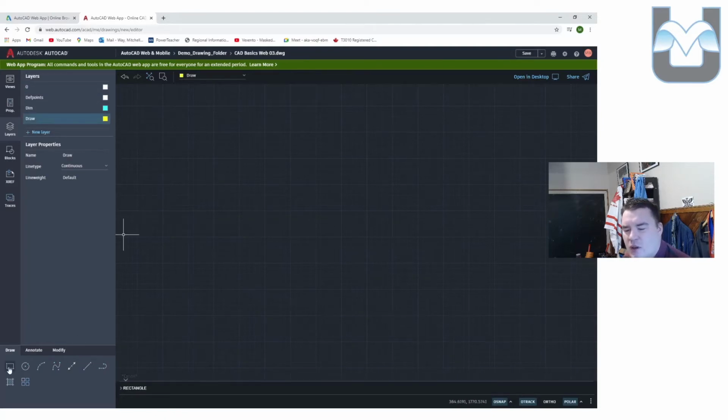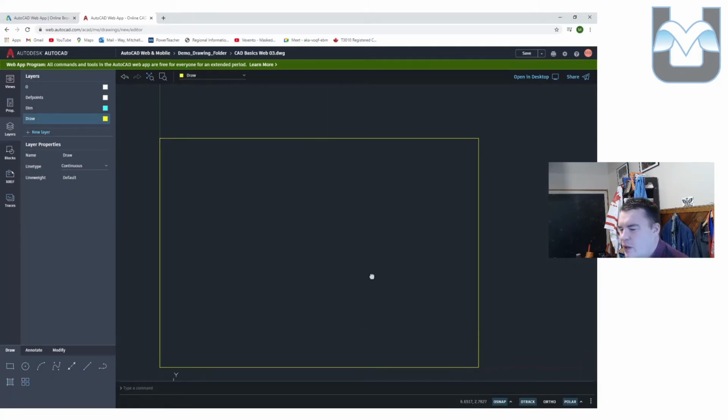We're going to start with our rectangle on the outside. We're going to go from 0, 0 to 10, tab 7, which is going to give us a little tiny rectangle. Let's zoom in manually here with the scroll wheel. And we are good to go.